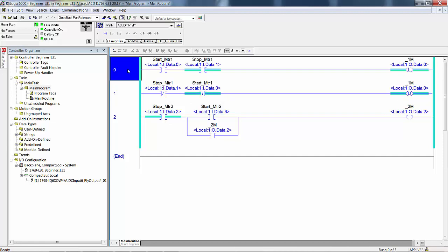So I'm online. So first thing I need to do is to go offline. Now I've already saved this, so I can just go offline. Now with RSLogix 500 MicroStarter Lite, if you use those development software packages, when you went offline or you did something where you should have saved it, it would almost always ask you if you wanted to save it. RSLogix 5000 does not ask you if you want to save. I just went from online to offline and it didn't give me a peep.